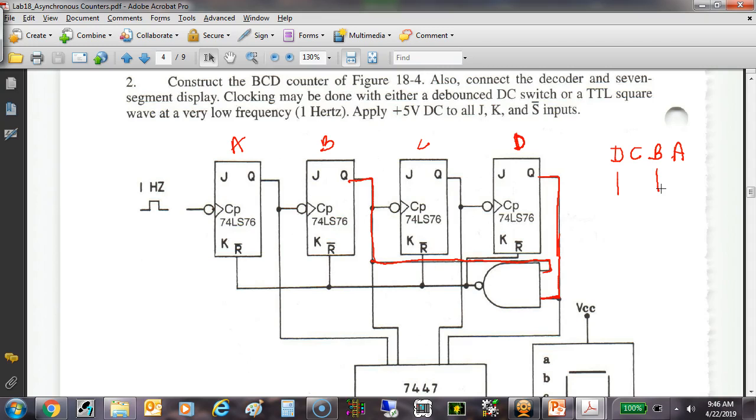Oh, it's truth table. Okay, because I'm looking at trying to figure out, if I'm just looking at it, how can I just tell? But I have to go to the truth table to know. A truth table for what? I know I'm going to reset on D. I know D is the most significant bit. I know A is the second bit, right? So I come over here and that's a 10, but we're never going to see a 10, because as soon as it tries to go to 10, it resets to 0.